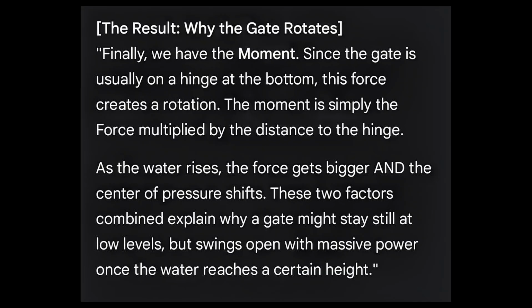Finally, we have the moment. Since the gate is usually on a hinge at the bottom, this force creates a rotation. The moment is simply the force multiplied by the distance to the hinge. As the water rises, the force gets bigger and the center of pressure shifts. These two factors combined explain why a gate might stay still at low levels, but swing open with massive power once the water reaches a certain height.